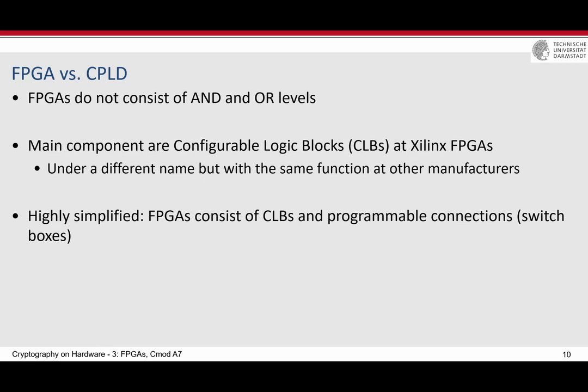Usually an FPGA consists of several CLBs, and we can configure the CLBs and also the interconnection between the CLBs. If you want to simplify things, FPGAs consist of CLBs and programmable interconnections. The CLBs are configurable, and the connections between them are also configurable and programmable.